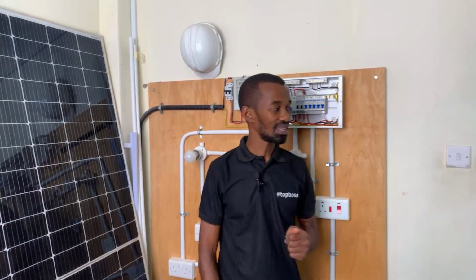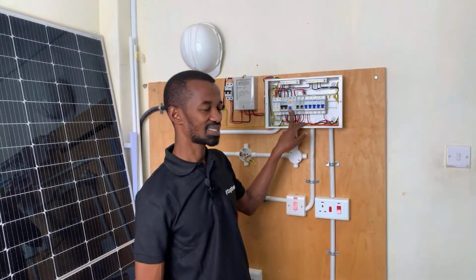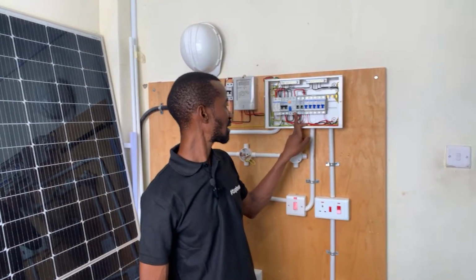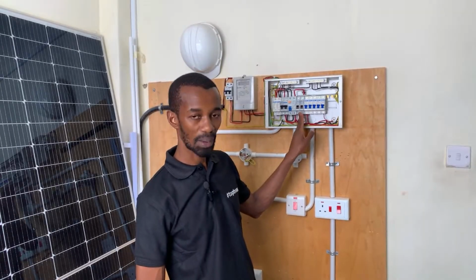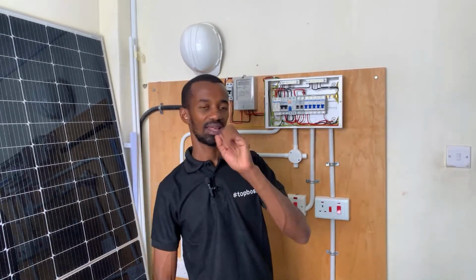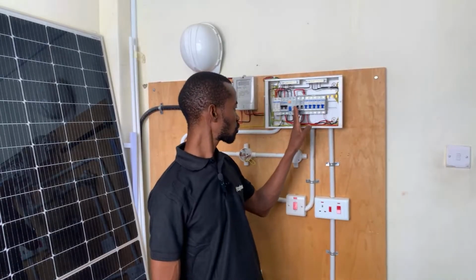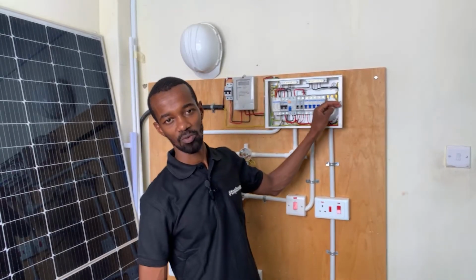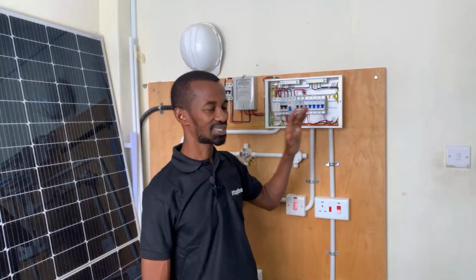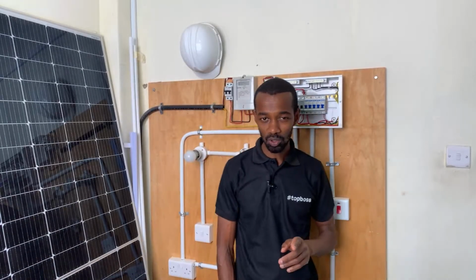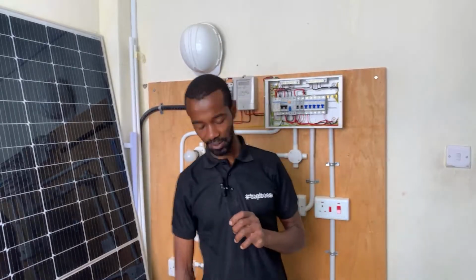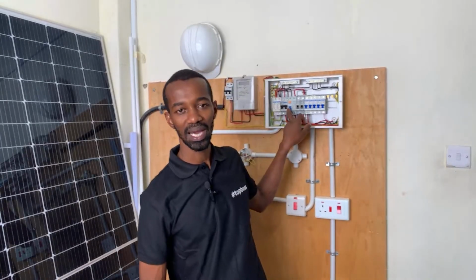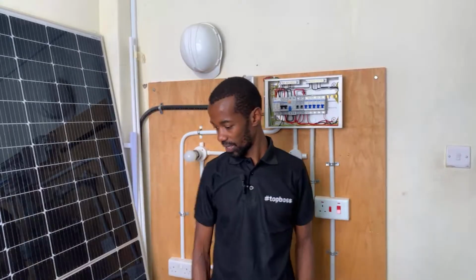It will definitely mean that this RCCB will trip and it will shut the entire supply of electricity or power in that home or that electrical installation. So every other thing will be shut off. But it is important to take note here that the wiring is very important. How that RCCB has been wired is very, very important.